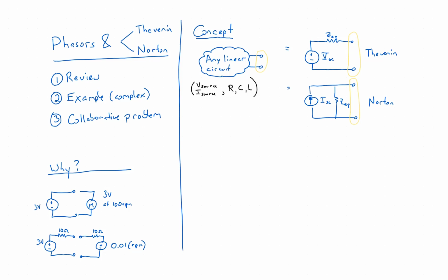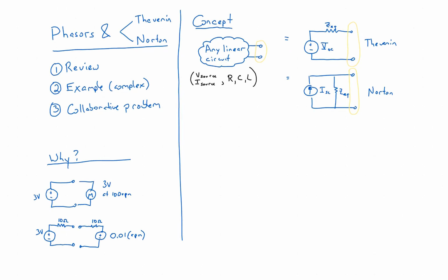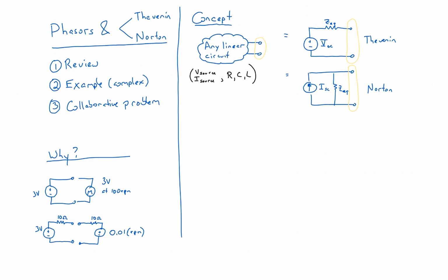And so you'd have to make sure it gets 4 volts. But you're not even supplying 4 volts, because there's resistance in the windings shown here, and there's a resistance inside the battery here. So of course, when you analyze this to find the resulting voltage across the motor, it will not be 3 volts, even though you connected it to a 3-volt battery. Thevenin models are really important in the real world, and you must understand how to find them.